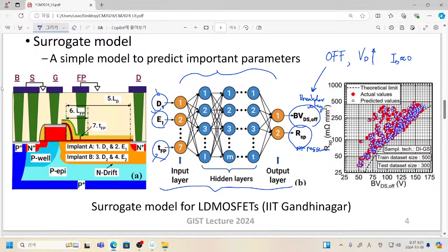However, if you have a certain physical implementation of your semiconductor device, then eventually when you apply too high drain voltage, there will be unwanted current conduction. So this condition, ID is very small, cannot be satisfied any further. That is called a breakdown, and the voltage where the breakdown phenomenon occurs is called the breakdown voltage.